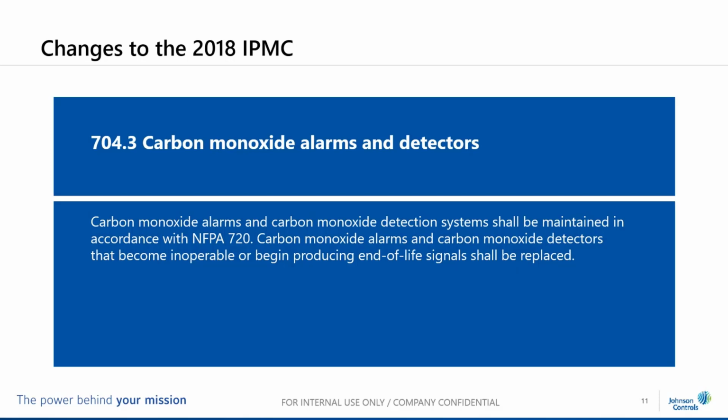Now, carbon monoxide alarms, just by their nature of how they function, have a finite life expectancy. There are some materials in there, and it varies by manufacturer, and some gases are put off, and then that gas is compared to the atmosphere that it's around, and the deviation gives us a report of carbon monoxide. But not to go into a whole lot more than that, the material that's in there has a finite life expectancy. Some are 5 years, 7 years, some are 10 years. It depends upon the manufacturer.